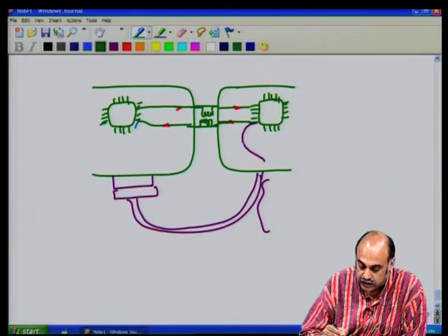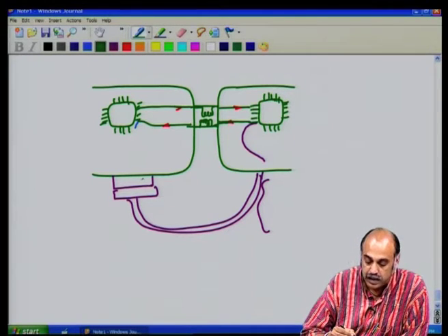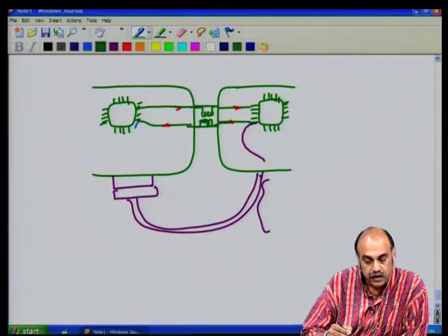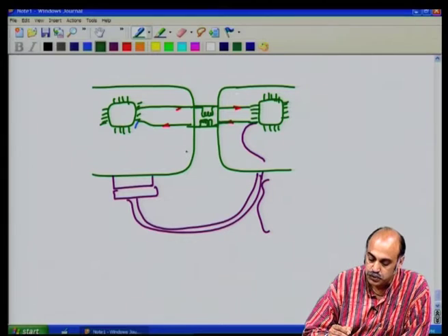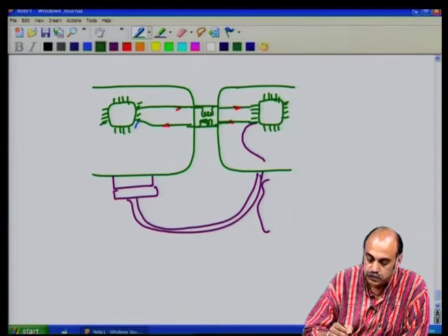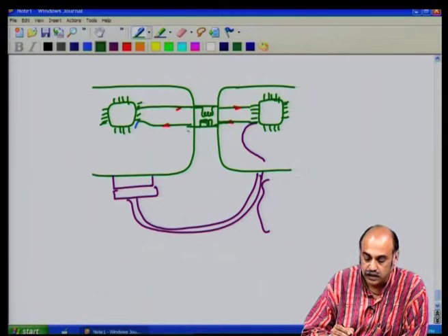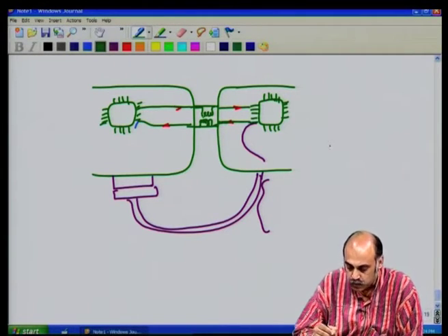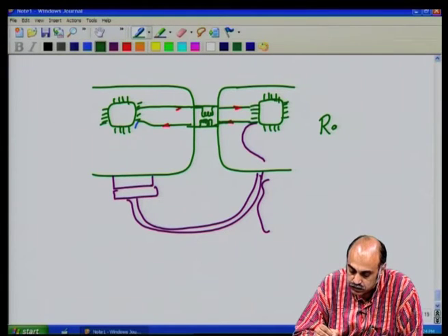So, therefore, the impedance of all other external paths will increase, and the impedance for the local path is reduced by putting this common mode choke, and thereby you try to retain most of the return path current here and reduce the loop area. So, the idea is reduce loop areas.